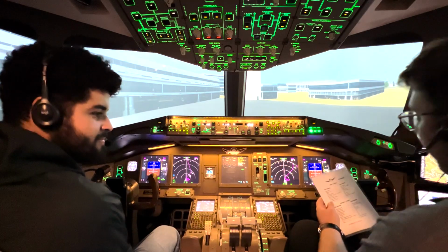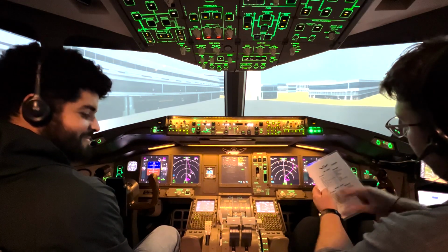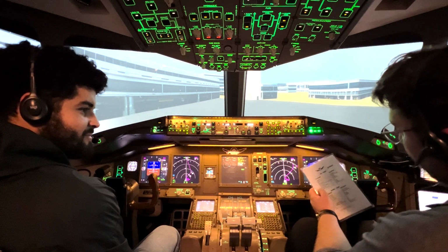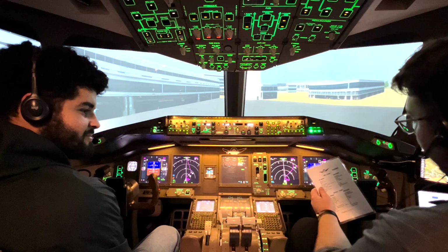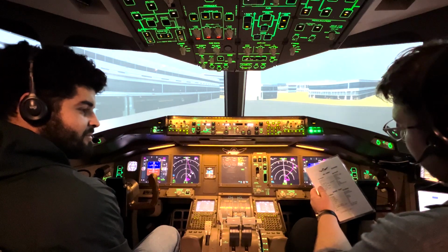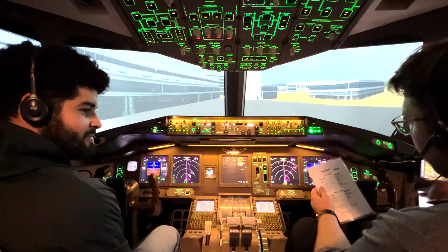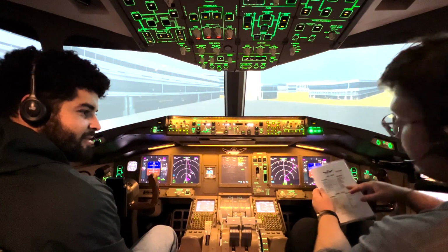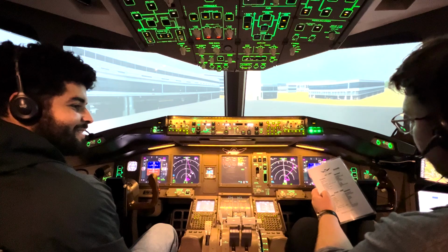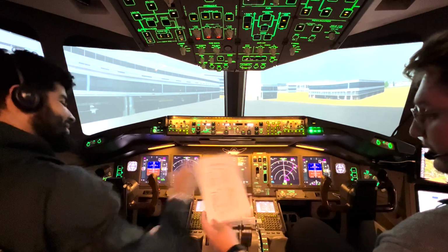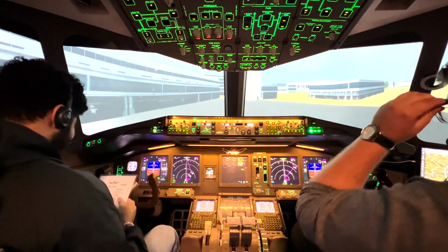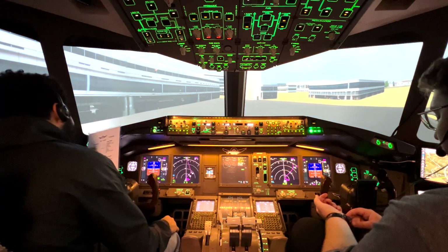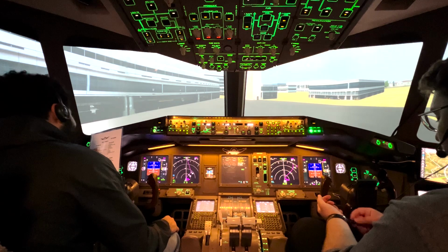So I will call for the pre-flight checklist, and then you will begin by reading inspection, and then I'll reply completed or not completed. Then you will say oxygen, and I will say checked, set, 100%. You will say FMC, and I will say loaded. So you get the idea. You challenge me with these ones, and I respond with these ones here. Perfect. All right. So let's go ahead and start. So I'm going to start off by saying pre-flight checklist. Okay, so the pre-flight checklist. We're doing this inspection, completed.